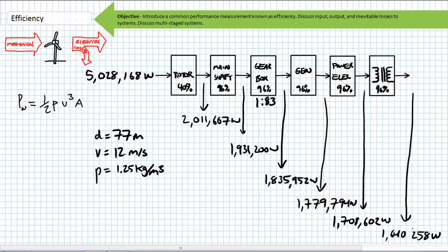The power in a column of wind is proportional to that wind's density, the cube of its velocity, and the area of the column. Denser air, let's say humid air next to a body of water, more power. Bigger diameter means squared bigger area, more power. Faster wind, lots more power, because it's cubic in nature.